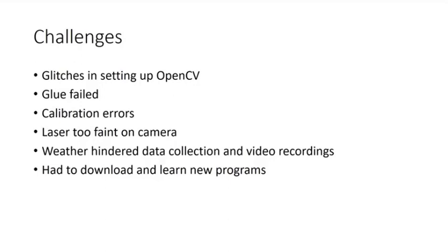Going past that, I had some errors with calibration. I couldn't get an HSV mask that worked properly, and I finally realized that the main issue was that I was using data that didn't have any laser return on it because it was too close to the Pi. Once I cut those images out and ran the calibration again, I was able to get a perfect setup.